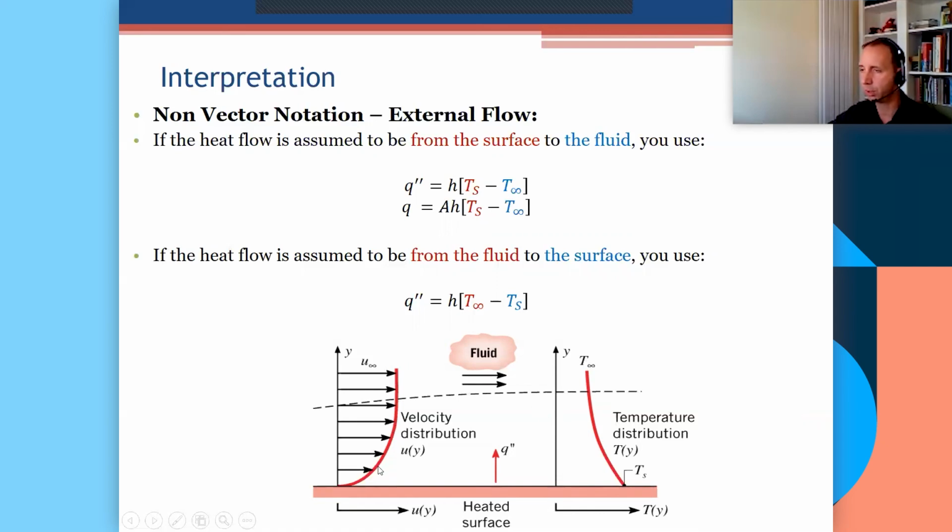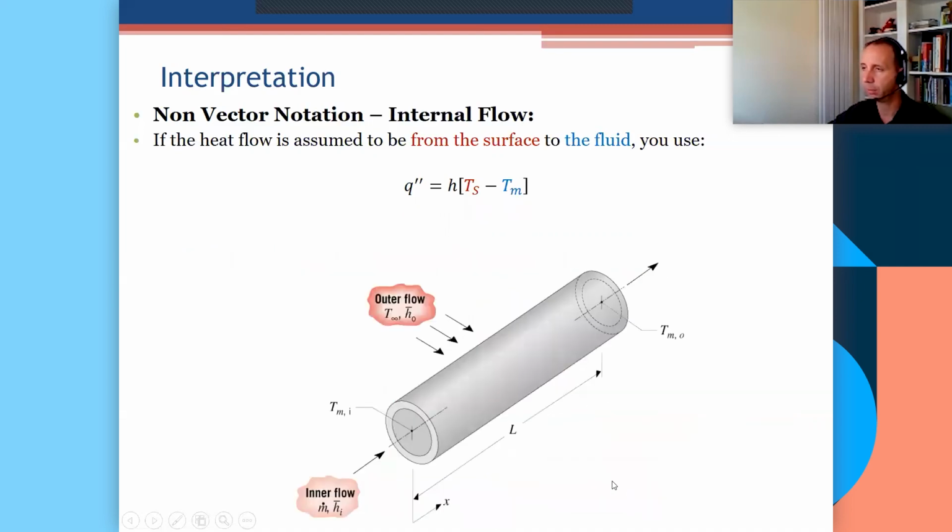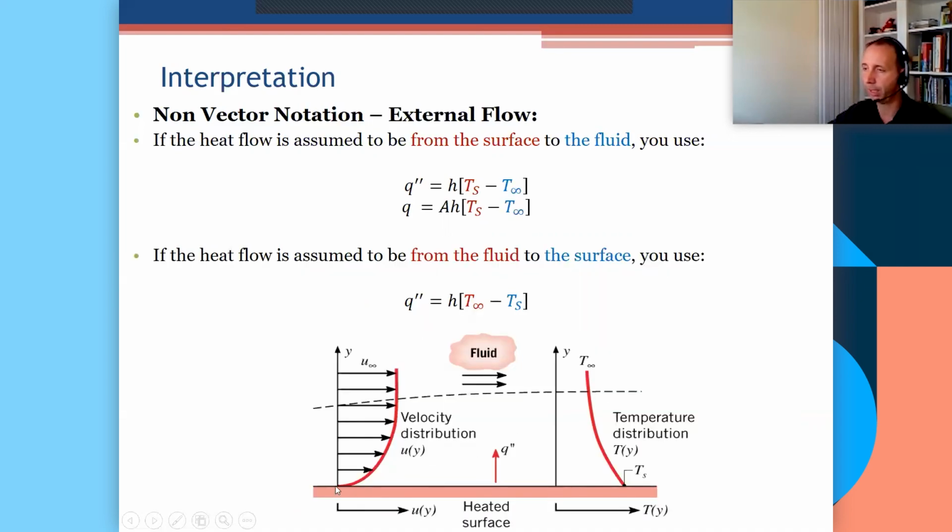And all these changes are taking place in what we call a boundary layer. That is a layer of fluid which is near the solid boundary. And we have different thicknesses of these layers. Generally, we say that the thickness is defined as the size of the boundary layer over which 99% of the changes are happening. So outside of it, we assume no influence of the plate, and we recover the free stream velocity. So that gives us the thickness of the hydrodynamic boundary layer, whereas on the thermal side, we have the thickness of the thermal boundary layer. We'll come back to all that later on.